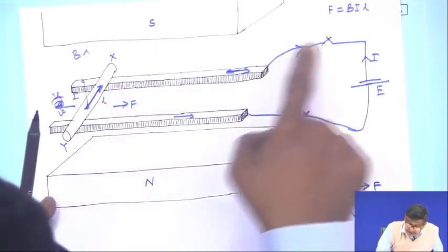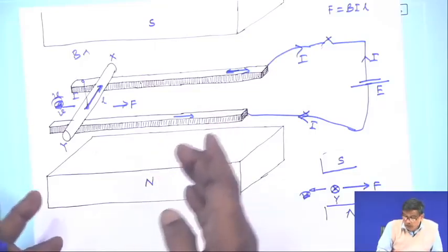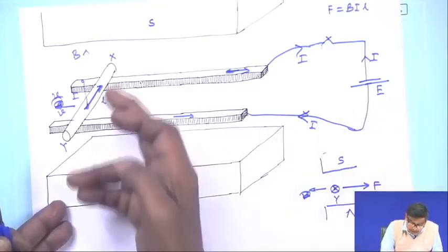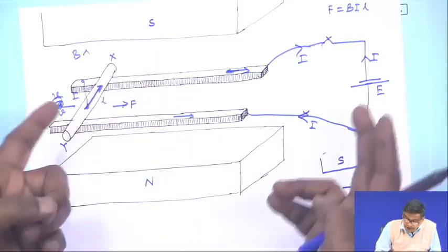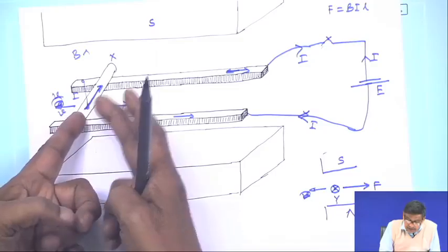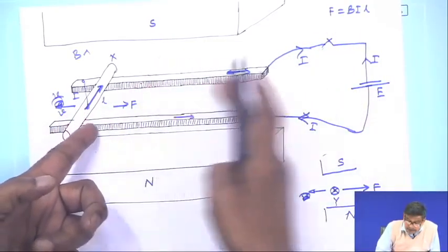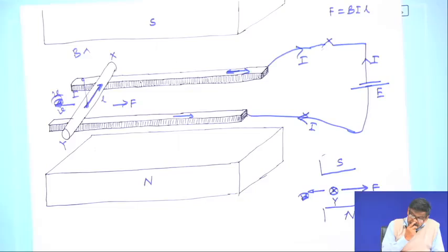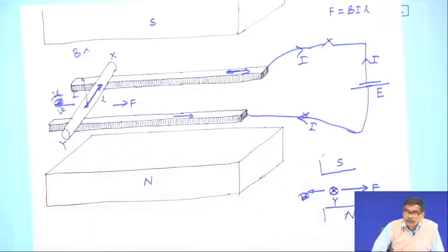Therefore, current in the circuit now is decided no longer by E alone, E is there, but between y and x it becomes a seat of EMF. The resultant of these 2 EMFs divided by the resistance of the path should decide the current. Therefore, people say both motoring and generating action goes side by side.